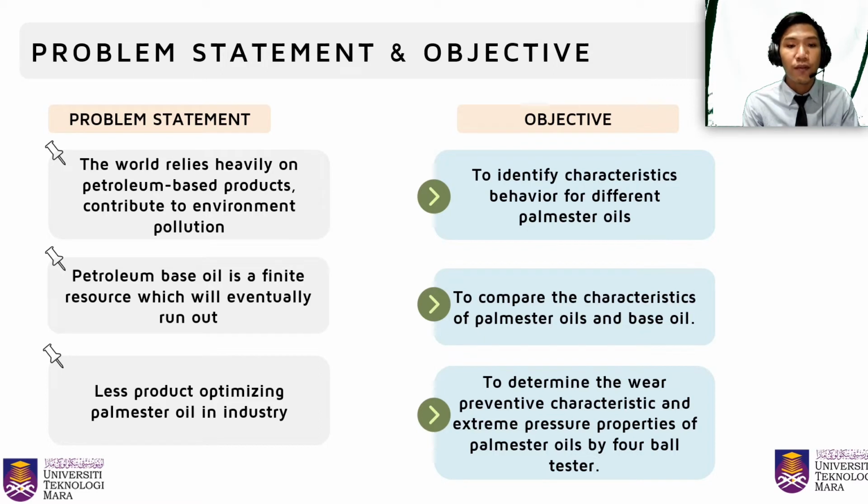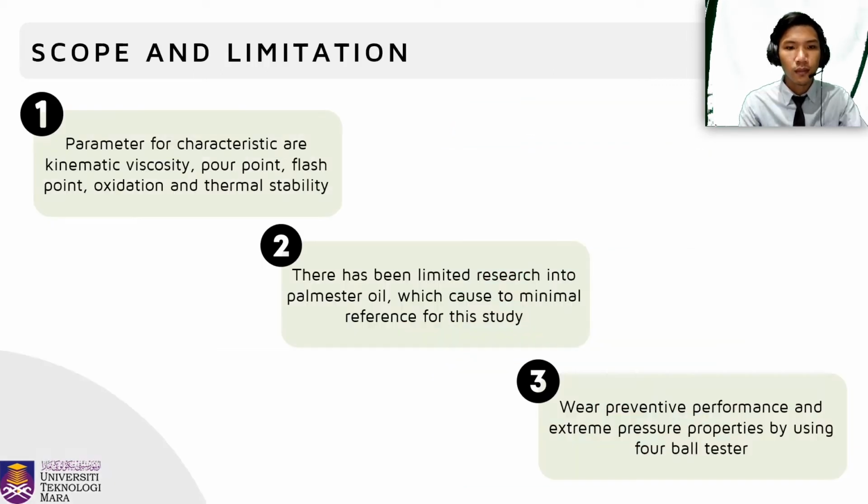The scope for this project is that the parameters are kinematic viscosity, pour point, flash point, oxidation, and thermal stability for comparison of palm ester oil and base oil properties. The tribology test of the palm ester will focus on wear preventive performance and extreme pressure properties by using a 4-ball tester.